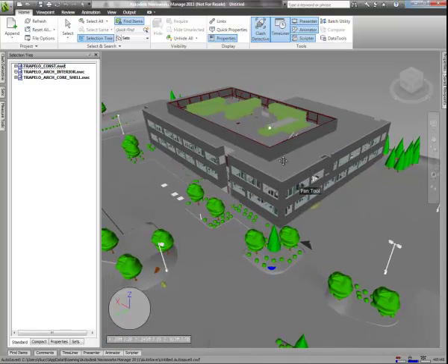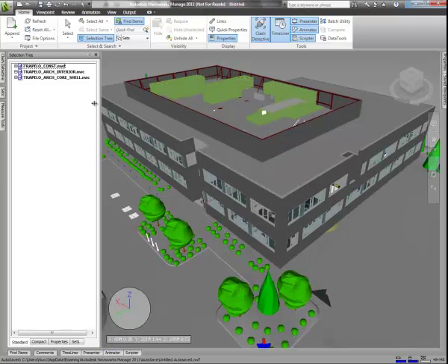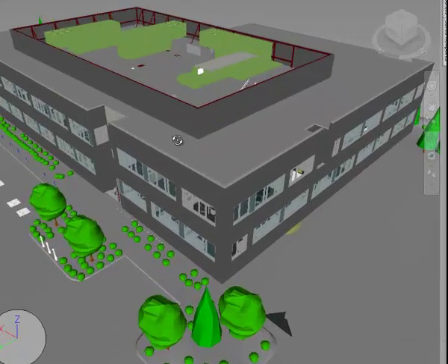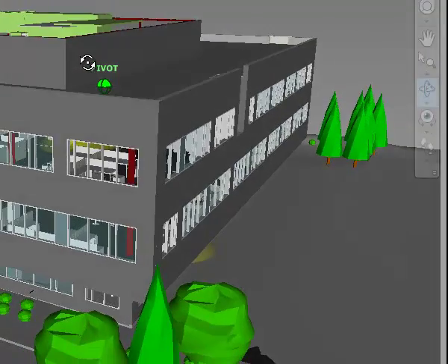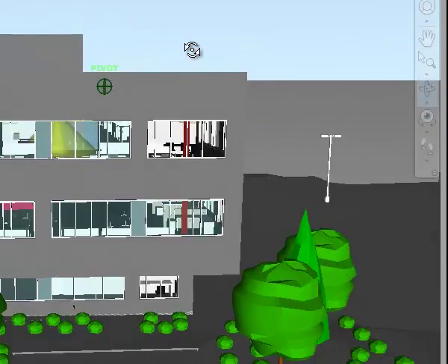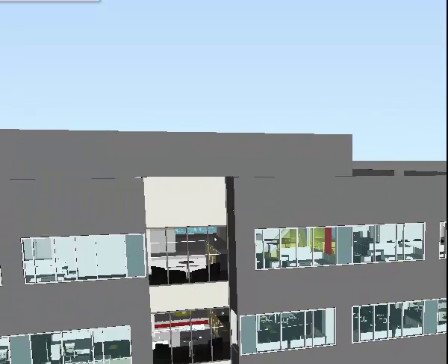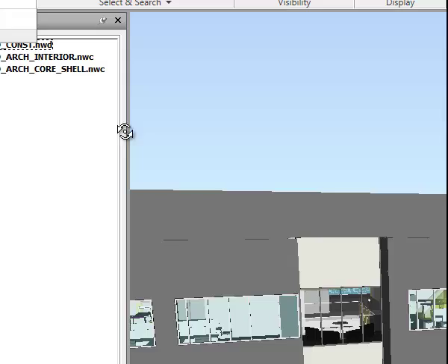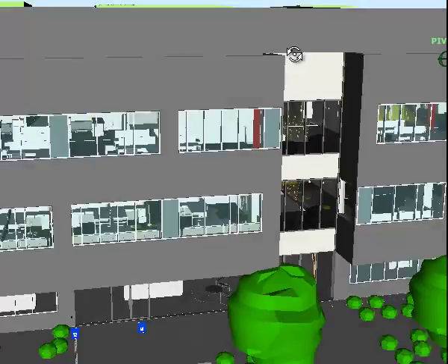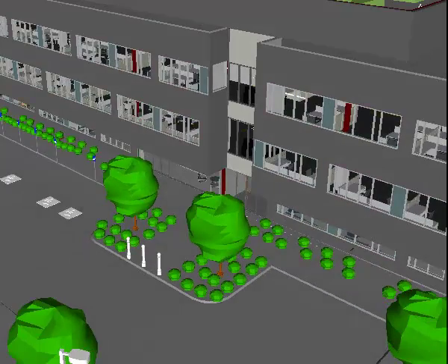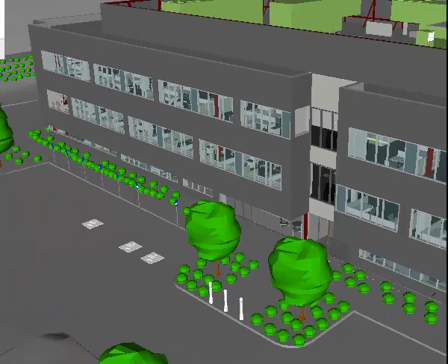Okay? So basically, I've created links to this geometry into my current NavisWorks file, and as that file might get overwritten, all I have to do is simply refresh. So here's refresh in the home panel, project tab. You have a bunch of different options on how to manage files that are appended. We also have an opportunity of merging geometry. If I merge geometry, essentially duplicate geometry is not going to be merged, but all of the markups and viewpoints created in previous files or other files are going to be merged.